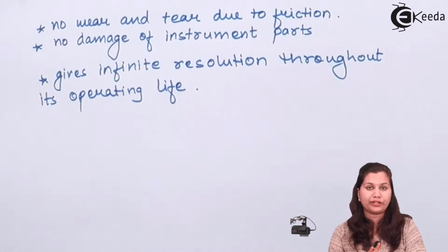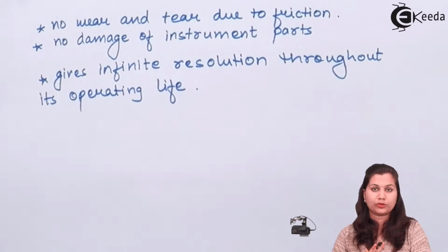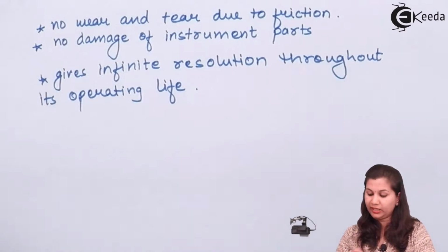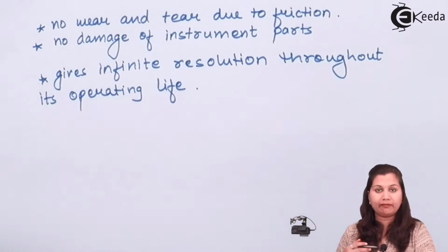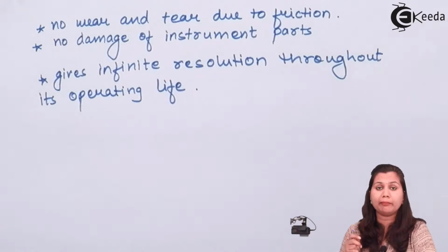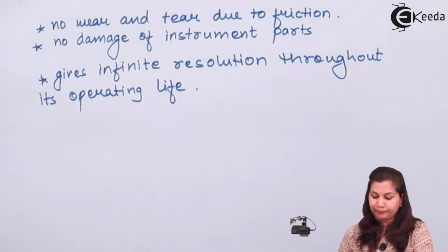So as no friction is produced, and there is electrical isolation between the core and the coils of the LVDT, this gives the LVDT an infinite resolution property throughout its operating life. Meaning very minute changes in the displacement can be accurately measured by the LVDT.